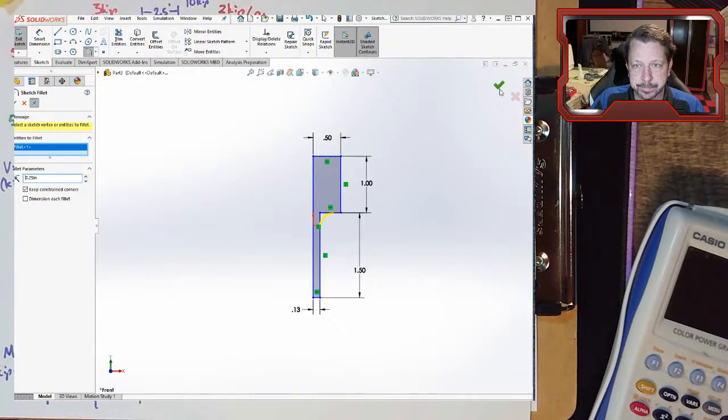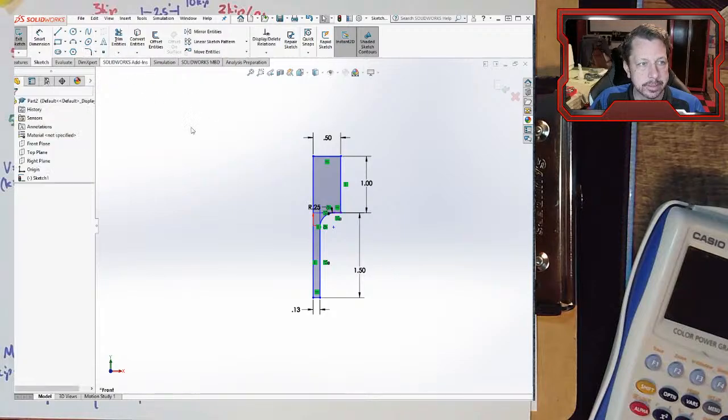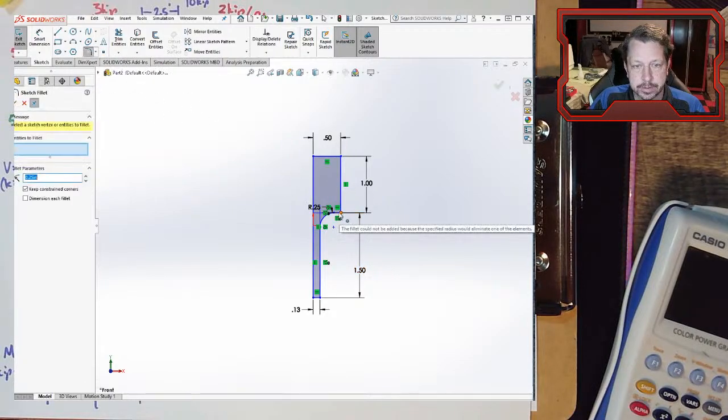All right. So this is 1/4 of our model. You could even fillet this corner if you wanted to, just to reduce the stress concentration over there. It's not a big deal. Can't be that big though.